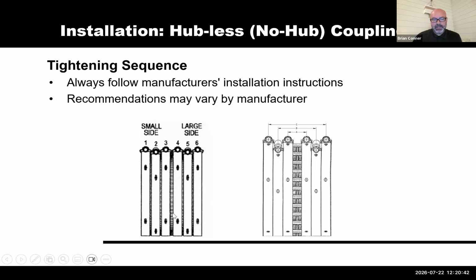And of course, this is a line drawing here, but you'll see that this one is a horizontal knurling pattern on this coupling. And then this one's got more of a woven vertical and horizontal pattern here. And through research, they found the best patterns for tightening these. Some of them may be directly left to right, depending on whether there's a smaller outside diameter to the pipe or the fittings. Or you could have recommendations that you would tighten a 3, 4, 2, 5, 1, 6 type of tightening sequence.